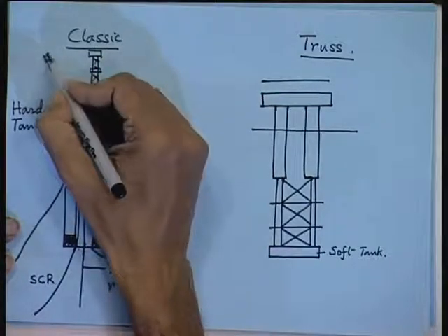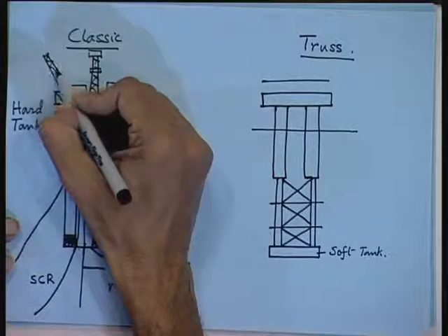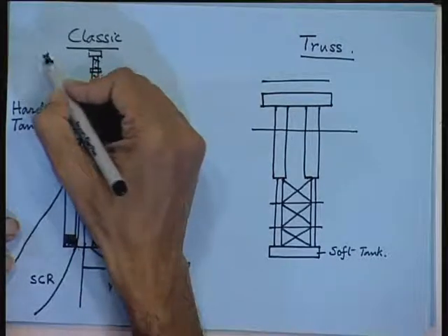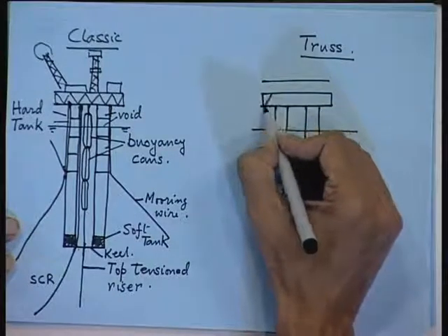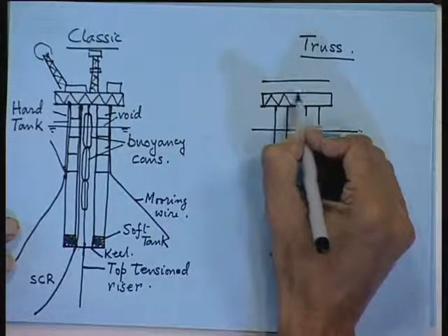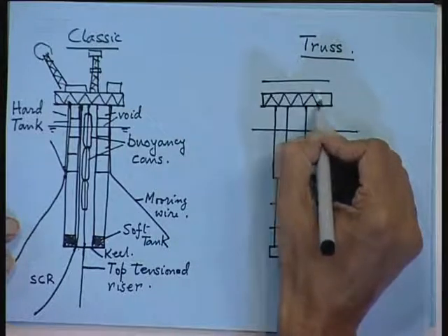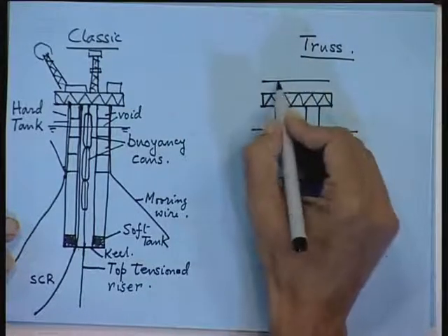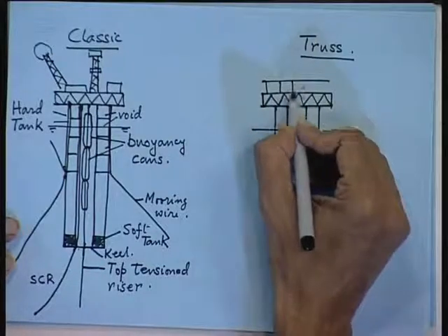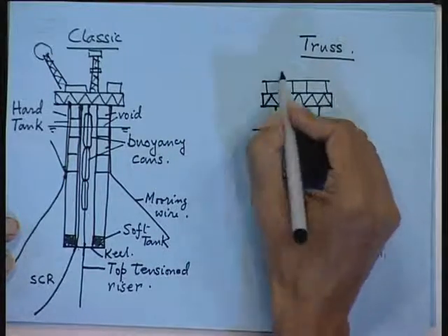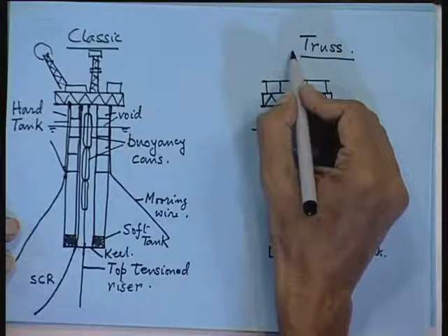but the spars you will find that they are not very big platforms like your say semi-submersibles or TLPs or FPSOs. They are essentially smaller compliant structures. So, these structures are called compliant platforms. So, that is they move with the direction of the waves.